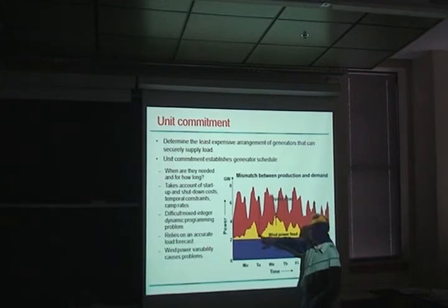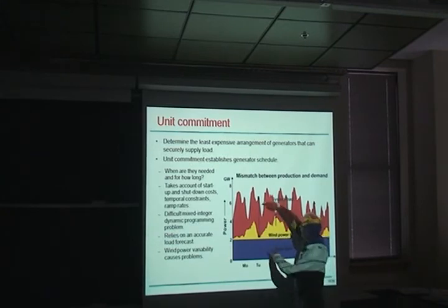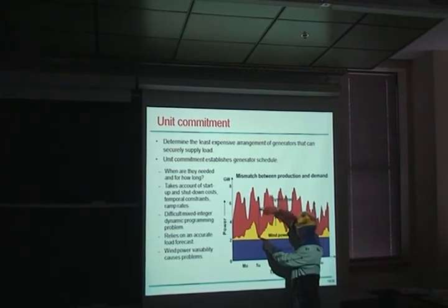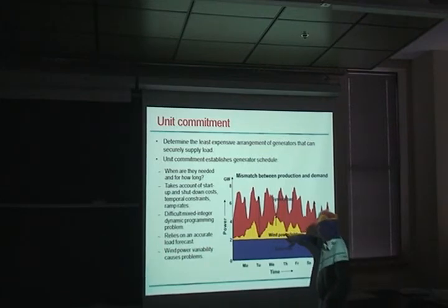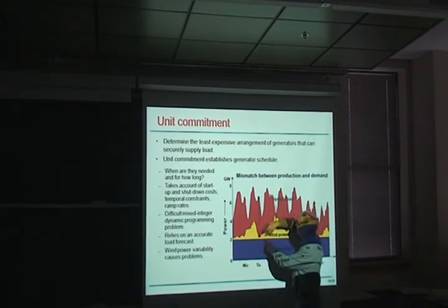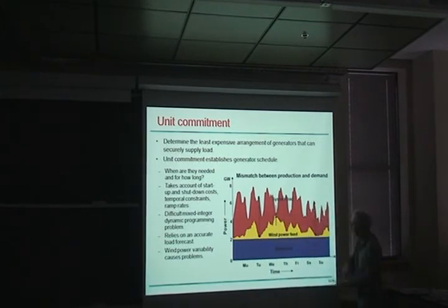But then you'll find other periods where the load is at a maximum and the wind is at a minimum, and there you need backup generation to cover that entire amount of capacity. Likewise, there's a large amount over here. So the variability in wind means that operators have to schedule plant to change from a large amount of traditional generation to a small amount, back up to a large amount, through daily and weekly cycles.